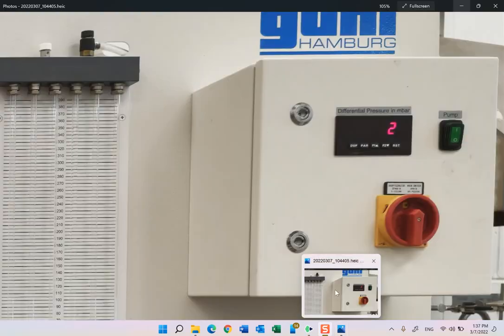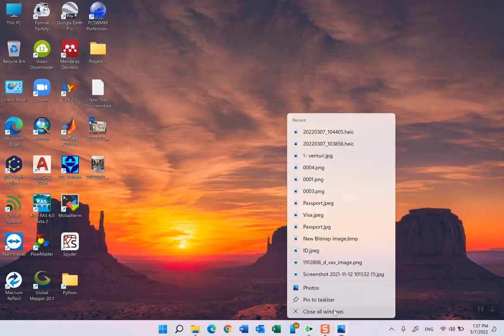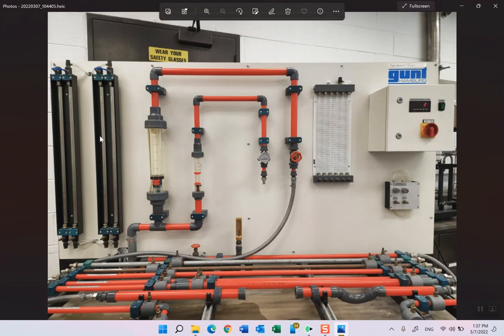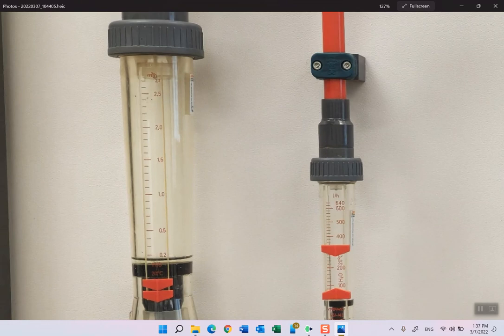This one here is the displacement meter, from which I can get the measured discharge. Anything else is calculated because you will use your calculator to multiply the area by the square root of something. That's why it's called calculated discharge. But the measured discharge, or the actual discharge that I know is actually passing through the system, can be measured from this equipment. And I'm going to show you how to do that in a while.